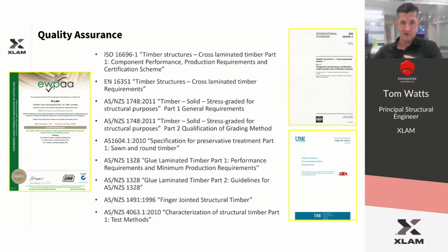So that sets out the broad framework of what CLT should be from a product point of view. And then the Australian standards listed below that on the screen are really how the component pieces of that CLT are graded, assessed, and glued together to form the CLT product. So you sometimes hear people saying that there are no manufacturing standards for CLT, which is really not correct. There's a lot of extensive information that goes behind this. Most of the components are within existing well-established Australian standards and certified by this overall ISO framework for the manufacturing of CLT, which is the same manufacturing standard that we reference for European manufacturers and others.